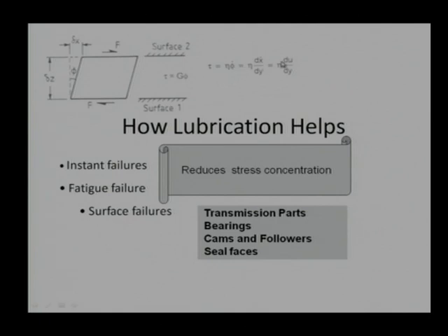The shear rate is expressed in terms of velocity gradient. Now, if I compare G versus eta, G is the modulus of rigidity or shear modulus, expressed in gigapascal for most materials, while eta is generally expressed in millipascal second. It is almost a difference of 1000 or more.